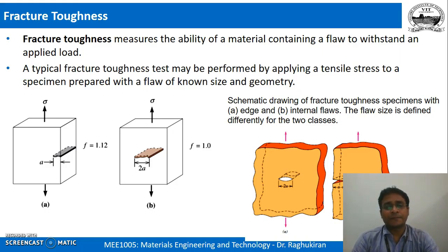When I say material defects, what kind of defects am I talking about? It may be just a processing defect, like when I do some casting, or produce it by employing some kind of processing or manufacturing technique, I may induce a lot of defects, like welding defects, where the material may not have joined properly.